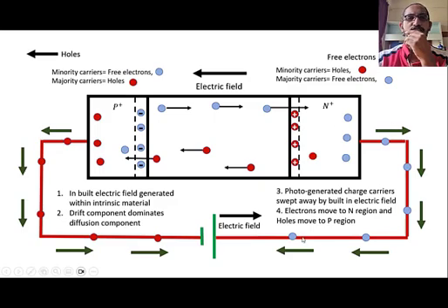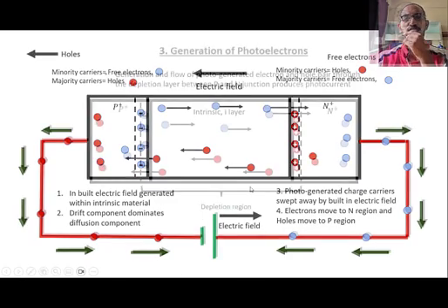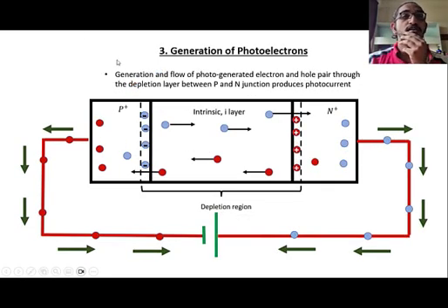This separation of charge carriers will then help to prevent recombination of electrons and holes. The last step is the generation of photocurrent. The separated charge carriers are then accumulated on the two metal contacts of the photodiode. The movement and constant exchange of electrons and hole pairs in the opposite direction between P and N region through the intrinsic material leads to the generation of photocurrent.